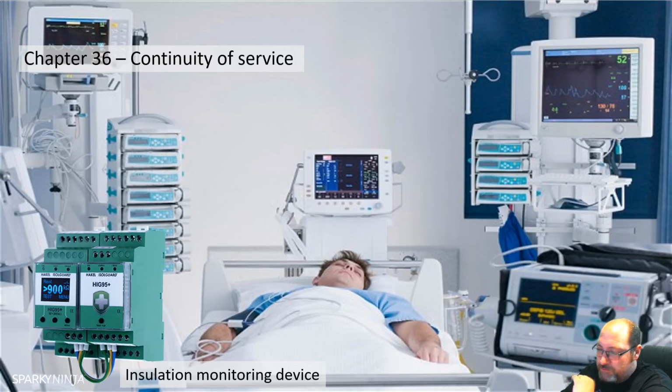So we have to think about the selection of the system earthing. The IT system might be a good idea. Select the protective device in order to achieve selectivity. So again, we want RCDs, then we need to achieve selectivity. Time delay RCDs, for example. Number of circuits. Divide the installation up into more circuits so that if there is an isolation, the other parts are not disconnected. In medical locations, socket outlets in medical IT locations or medical operating theatre locations are often supplied by two separate circuits, so that if one was to fail, the other one is still there. Multiple power supplies, that's what that is, and the use of a monitoring device. So there are a number of ways to achieve continuity of service, and we'll cover them later on in part 5, and we'll also probably preview them in section 7.10.